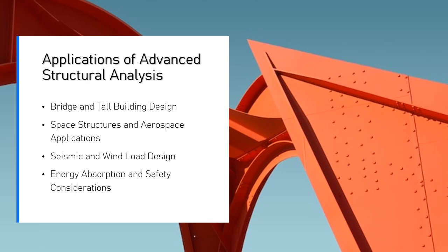Challenges: tall buildings and structures like the Burj Khalifa must resist lateral forces generated by strong winds, particularly in areas subject to hurricane-force winds. These forces act across the building's surface area, inducing vibrations, deflections, and shear stresses. Advanced analysis. To evaluate the aeroelastic response of the structure, computational fluid dynamics, CFD, and wind tunnel testing are used. Dynamic analysis using finite element modeling helps simulate how the building responds to different wind speeds and directional forces.